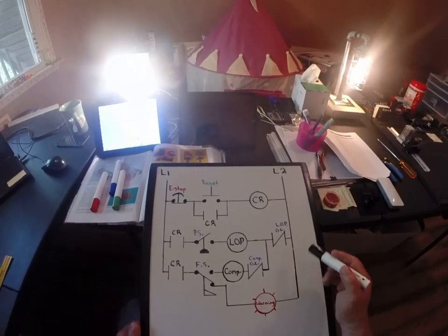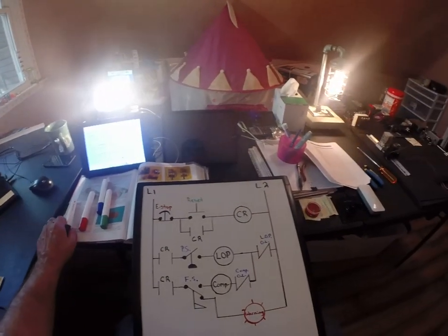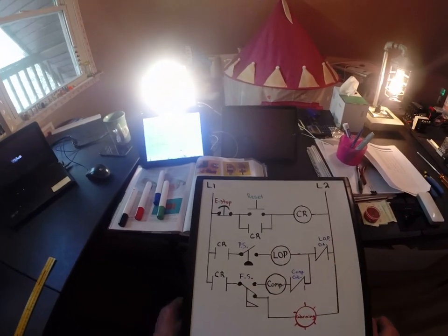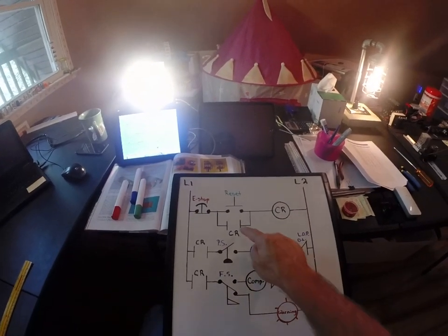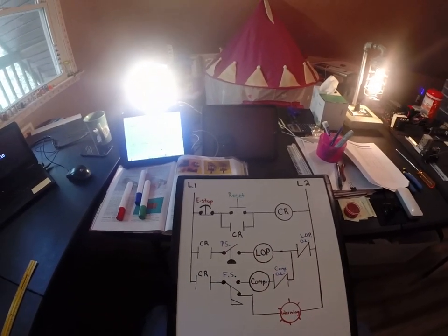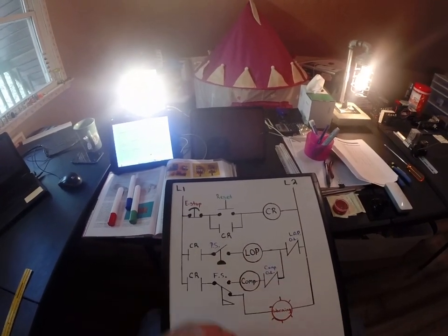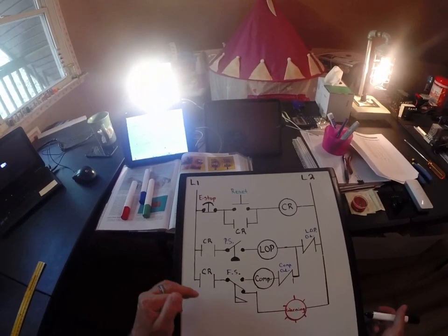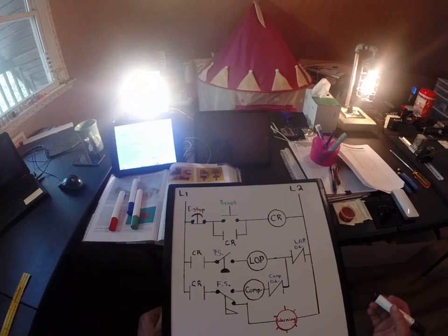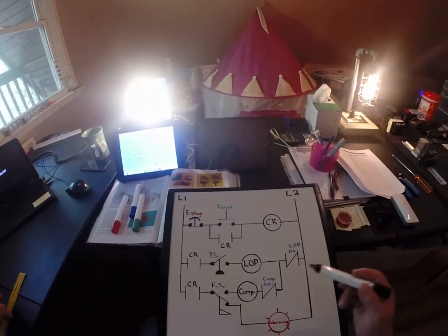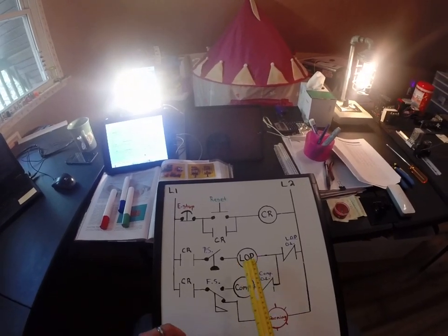The reason why I'm making this video is because in our lab, if we want to simulate this, we don't have relays that have 3 sets of normally open. All of our relays have 1 set of normally open and 1 set of normally closed, or 2 opens or 2 closed. So how do we make this work in lab? Well, a couple different ways. We could eliminate this other contact and just draw 1 line, or the best way of doing this is to make this a little more interesting.